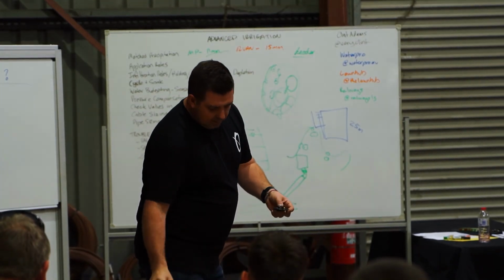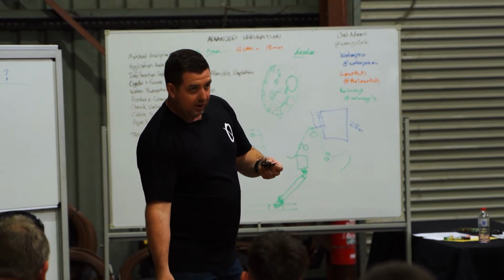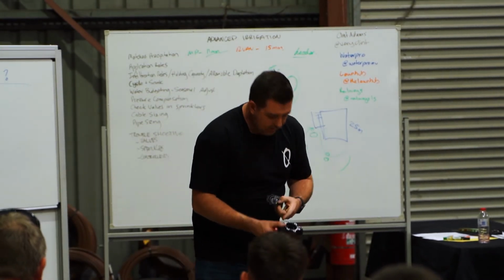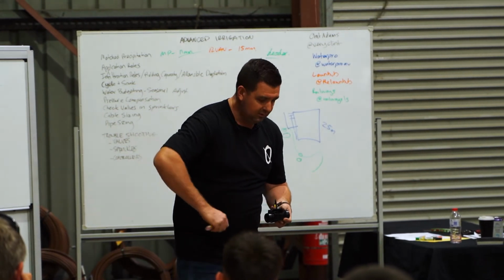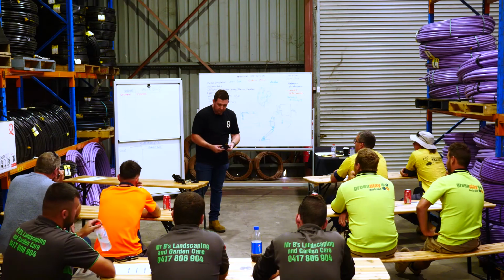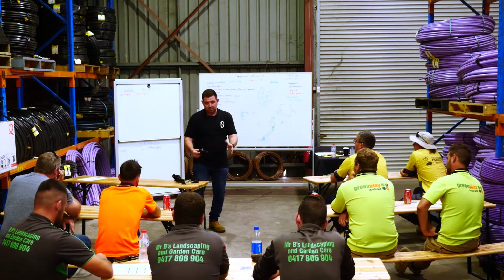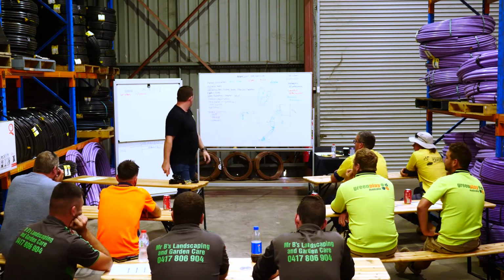So if you want to check for a blockage, you'll take that out, and it's just looking through here. That's when you'll open your valve. So you'll have your ball valve off to do this, open it back up and flush some water through it. If that's all clean, you put it all back together, it should be fine. So that's the water.